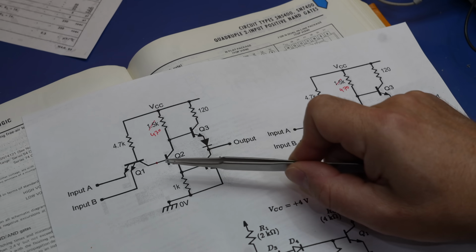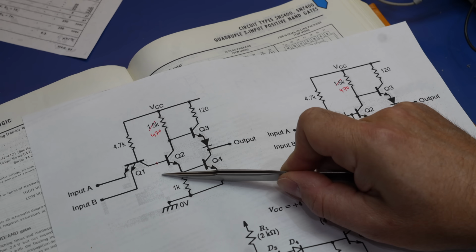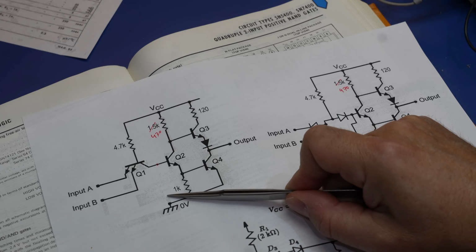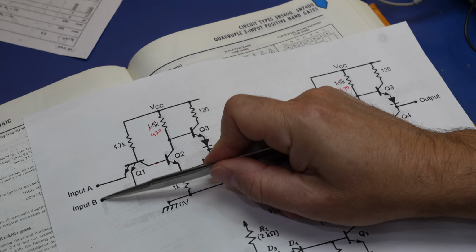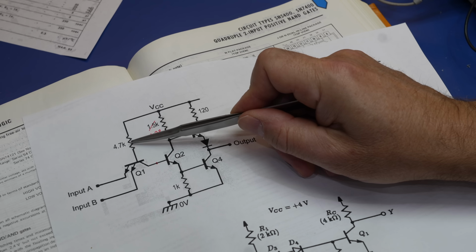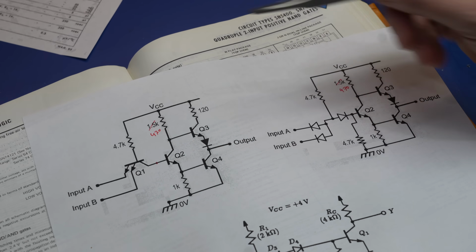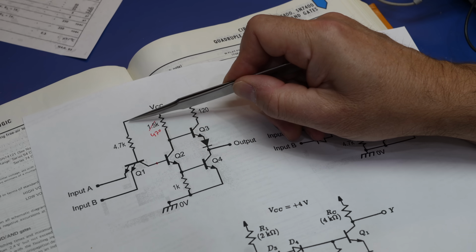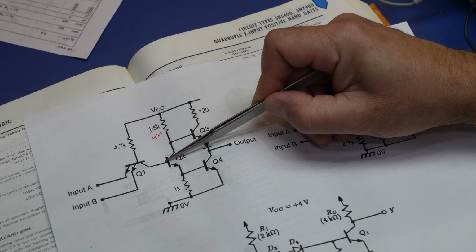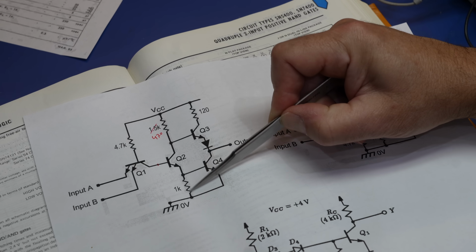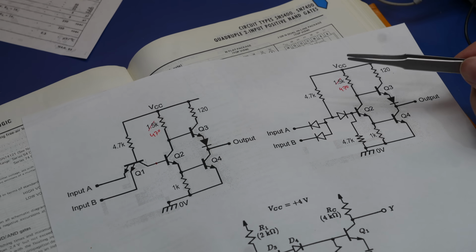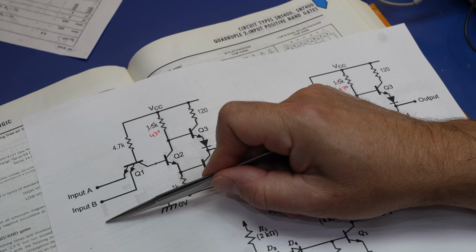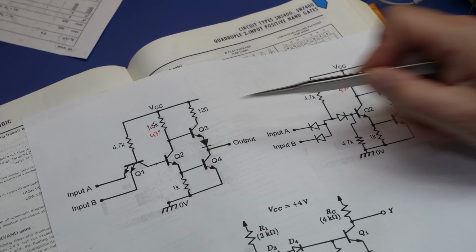So this transistor, which is the key to the TTL, is really used in a very weird way. Q1 behaves neither like the DTL nor like a transistor. It's in between. It has the two modes. When the inputs A and B are high, there is no current going through the base, then it actually behaves like the DTL circuit. This diode is blocking and this diode is conducting. There's current that passes through Q2 and turns it on. However, as soon as input B or input A goes low, then this transforms into a transistor, so it behaves very differently.